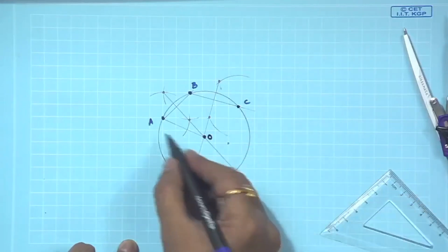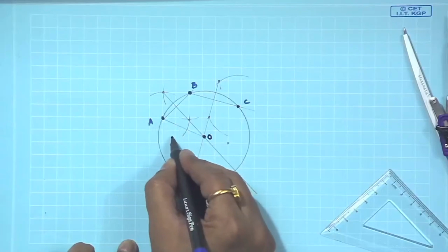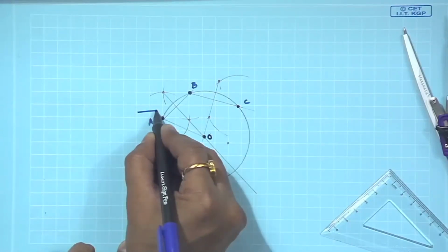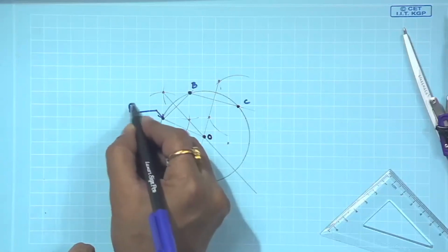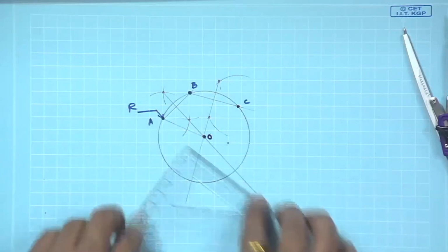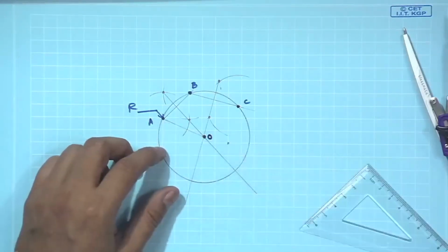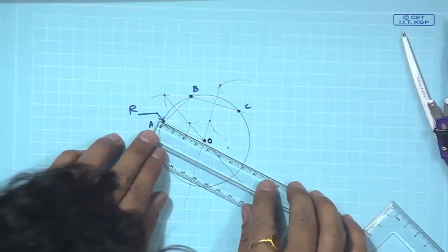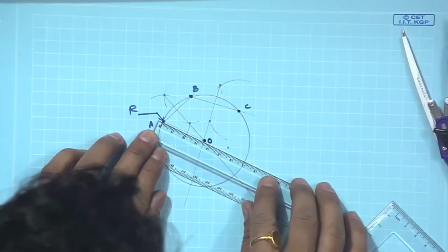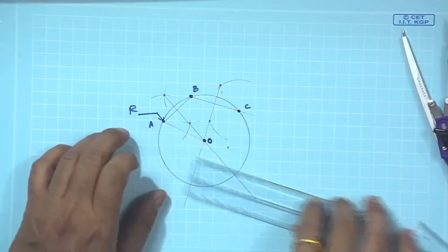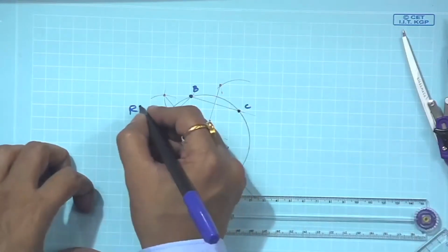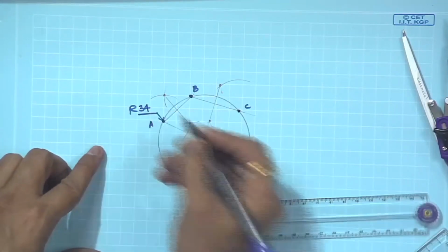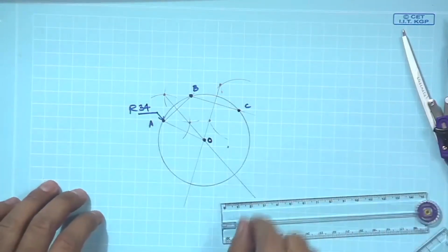If one requires the distance, AO is the radius of that circle, something like the leader lines we show, whatever the units. Let us measure it using our scale. This is something like 3.4 centimeters. So, we use millimeters as the notation, R 34 for that circle.